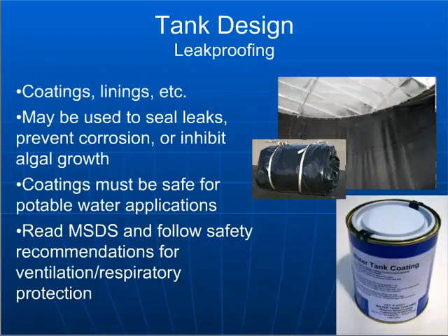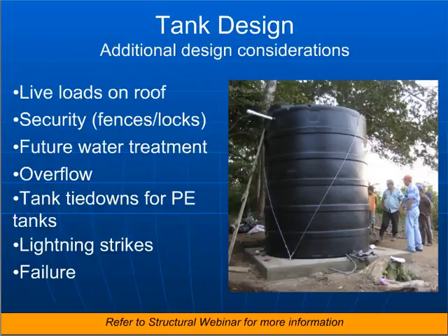The tanks typically do require some kind of leak-proofing or lining. There are a few different ways of going about that, but again, I think relying on the knowledge of local contractors, local masons who have built water tanks before, they're typically going to know what is available in your area and what has been used successfully in the area that you're working.